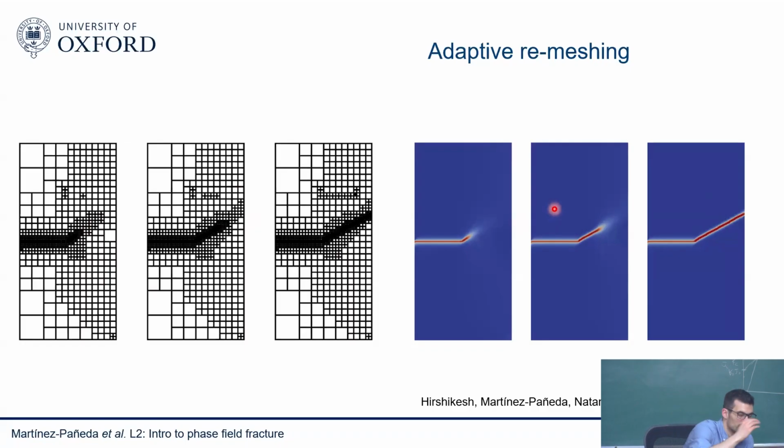Yes? This type of meshing I see is always rectangles in only one orientation, which means a crack face is always a step staggered. But in this method, you don't have to have full elements cracked or uncracked. This is the problem with local continuum damage mechanics. Here it is nonlocal. So the extension of where the crack is going to be distributed depends on the length scale. And therefore, you're not going to have elements that are either fully cracked or uncracked. You could have an integration point that is fully cracked and another one that is not, in that sense. So you don't have a staircase.